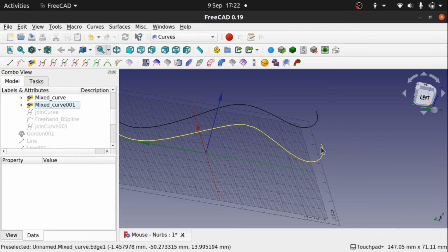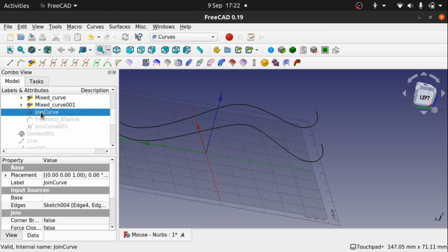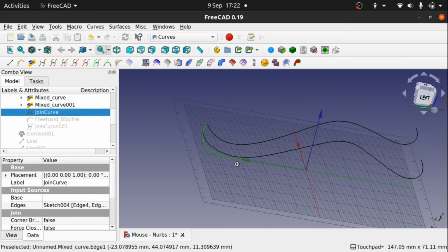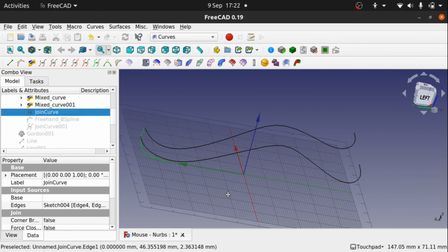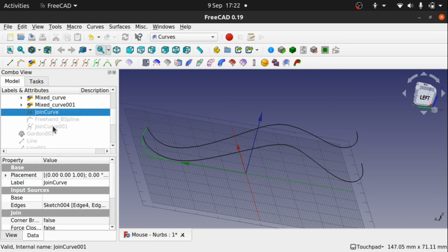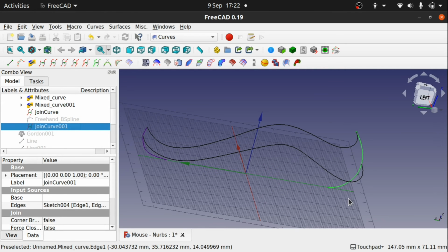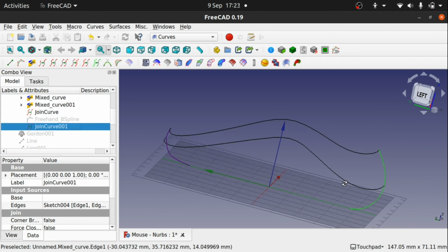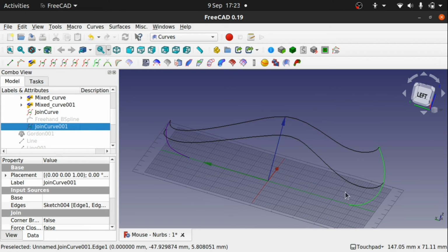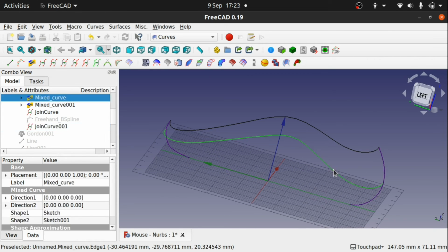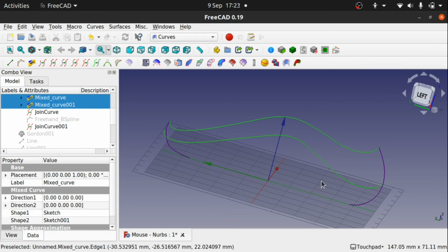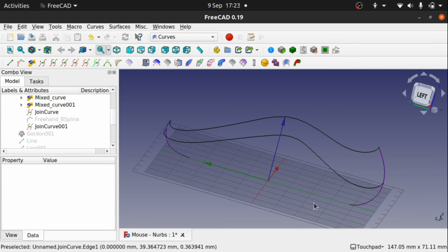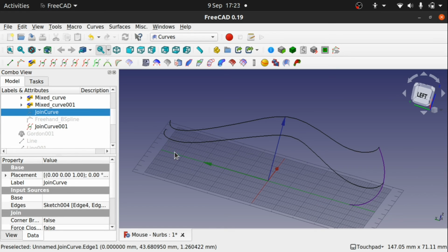We need to bring in this curve again. So bring in that join curve, which is this side. And also bring in the join curve on the other side. Now, we're going to create a ruled surface across here. We can create them by using these two and creating a ruled surface and then sweep across two rails using these rails. These curves down the bottom here, because they've gone beyond, may affect it. If it does, what we just need to do is just hide those again.